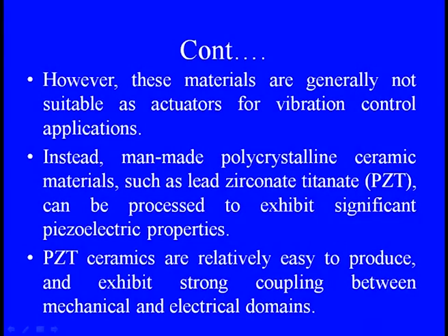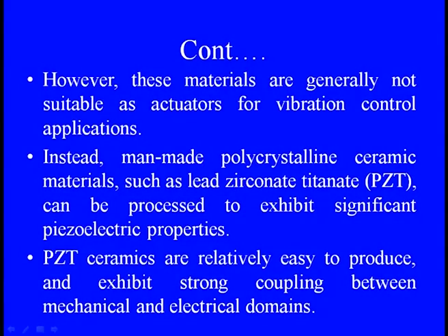PZT can be processed to exhibit significant piezoelectric properties. So, this is the man-made polycrystalline ceramic material in which all three materials, the lead, the zirconate and the titanate, exhibit excellent features required for the sensing and actuation feature. So, PZT ceramics are in the category of polycrystalline ceramic material. PZT ceramics are relatively easy to produce from a manufacturing point of view, and can also exhibit strong coupling between the mechanical and electrical domains, when we are trying to change mechanical energy to electrical energy or electrical voltage into mechanical strain.